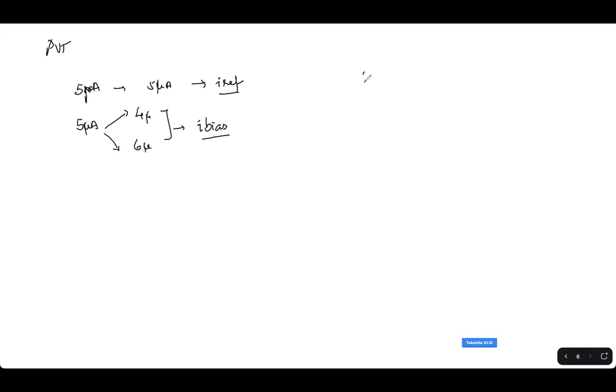Very similarly, if you say 1.2 must always be 1.2, it will be a VREF. Let's say you generate 1.2 as typical, but 1.1 to 1.3 across corners. In such a case, we may call it V bias. Both are very much useful. Both VREF and V bias are used very widely in all the circuits.